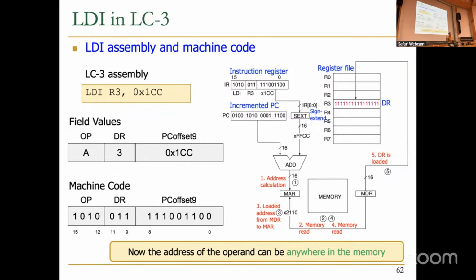And for example, the original MIPS actually didn't even have a multiply instruction. It didn't even have a load byte instruction. They started with load word. Quickly, they figured out, bad idea. People use multiplies all the time, so we cannot just have adds and shifts. They also figured out quickly, loading words is not enough, bad idea. People load bytes all the time, so let's have a load byte. So over time, that ISA becomes more complicated. It's still not that complex as you will implement in your lectures. But this is the idea.